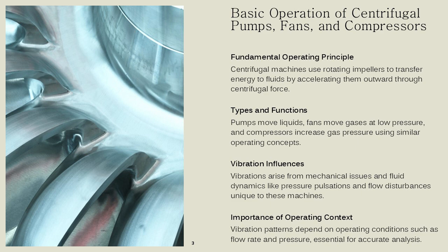Understanding the basic operation is essential because vibration patterns are strongly dependent on operating conditions such as flow rate, suction pressure, discharge pressure, and gas or liquid properties. Small changes in these parameters can significantly alter vibration amplitudes and frequency content.